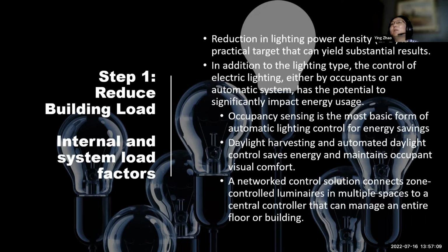When people leave the space for lunch, the light turns off, and it also sends a signal to the HVAC terminal, which can reduce the temperature set points.